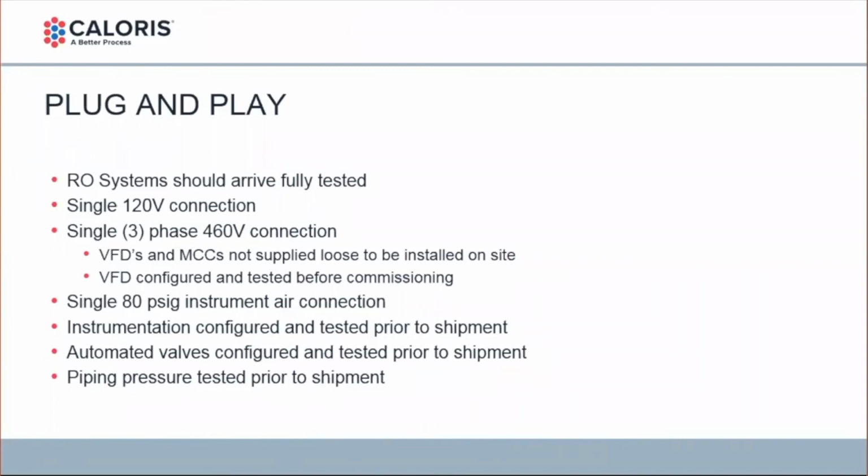What that requires is a single 120 volt connection and a single 3-phase connection. The VFDs and MCCs should not be supplied loose. The VFD should be configured and tested before commissioning.